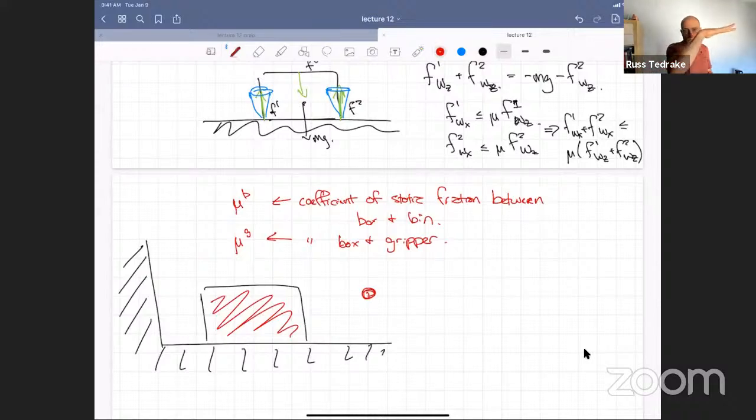But at the moment before you start putting your foot down, a robot like a Boston Dynamics robot that can do force control tends to go into a force control mode. And there's a reason for that we can see here immediately. As I start programming my force control only, I'm going to lop off the inverse dynamics and just command forces directly first, just to understand that.